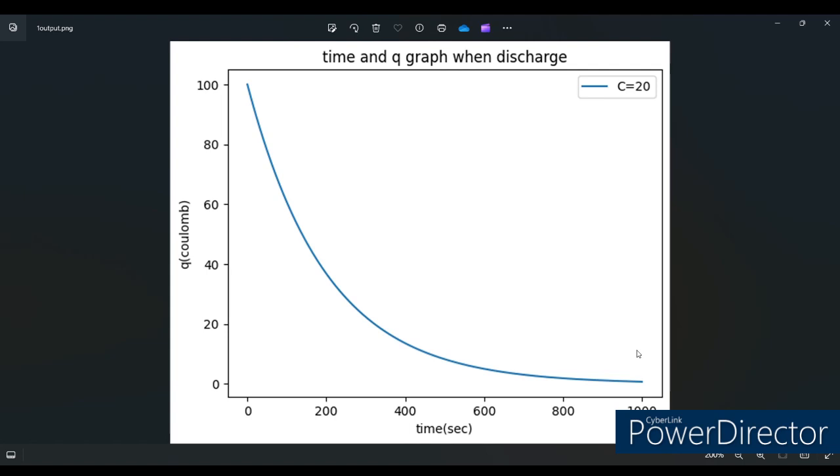To measure the capacitor, we know that when t equals tau equals RC, V of t equals 0.632 V max. By using cursor mode, we get a value of capacitor.